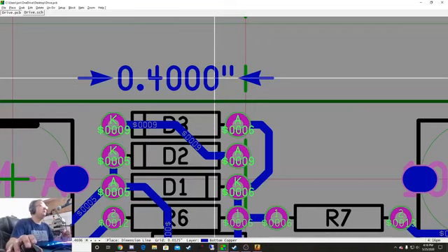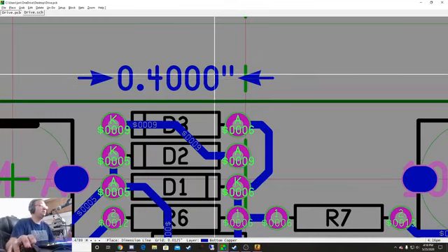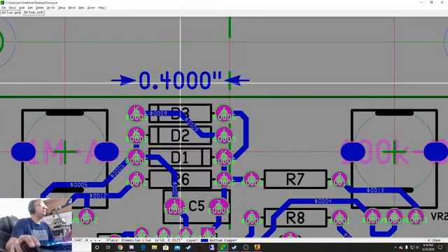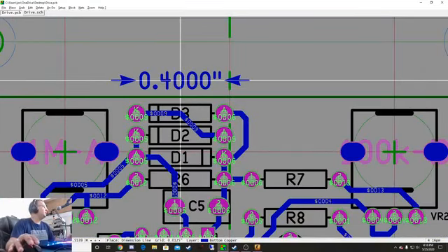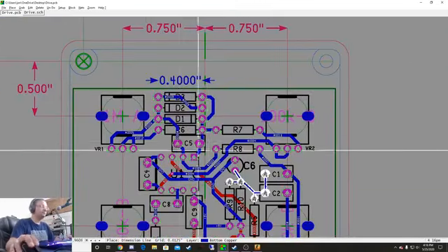So if you're having somebody like me build this for you, and you have all your components at 300 thousandths, I'm going to no quote it, because if I have to build it, I have to hand bend every part just like you are, and I can't save you any money because I can't machine build it. So please, when you're doing a new layout, put all your components whenever possible at 400 thousandths.